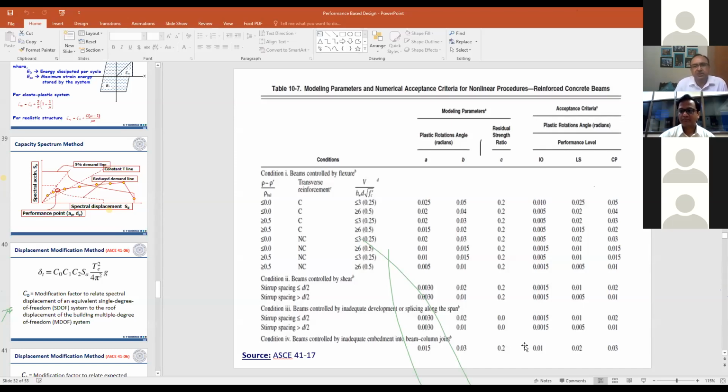Now coming to the specific questions of, let us say, slab, when we have rigid diaphragm action of the slab. In India, we have mostly monolithic slabs. So when we have monolithic slabs with frames and shear walls, in that case, the slab will act as a rigid diaphragm. And this modeling of rigid diaphragm is important, not only in nonlinear analysis, even in linear analysis. So in linear analysis also, this rigid diaphragm should be modeled.